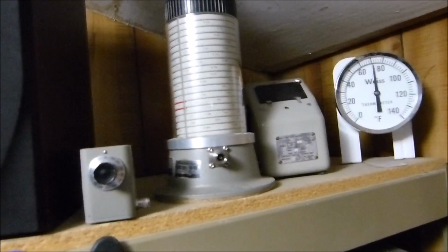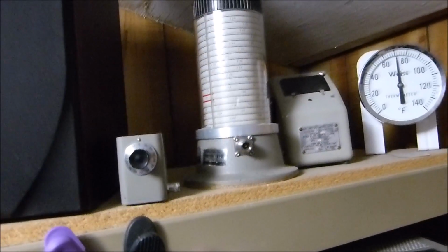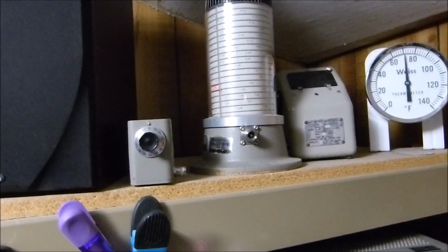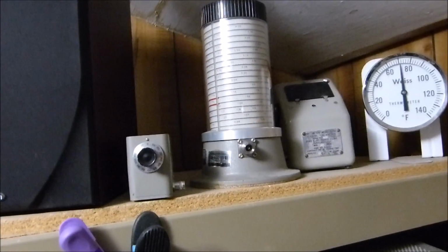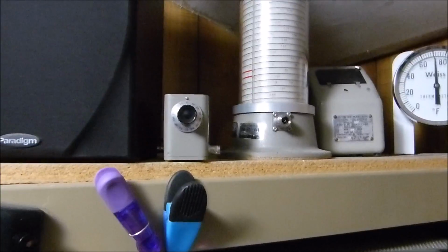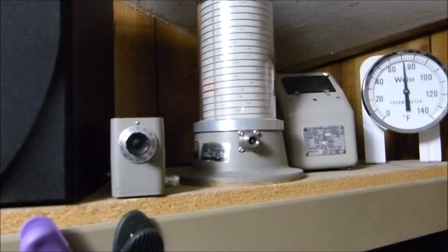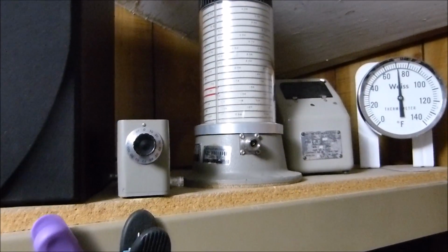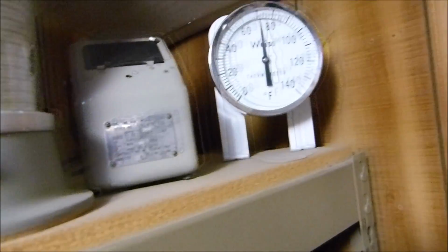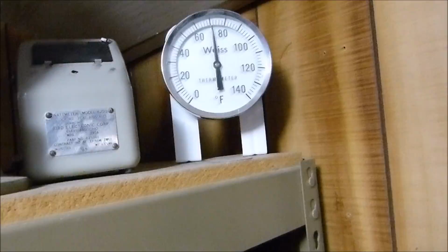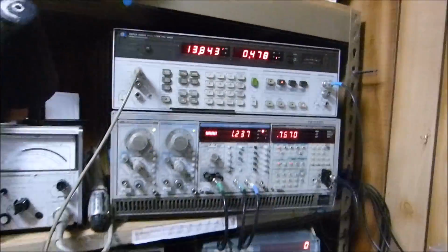There's an old frequency meter right there that you've got to use a detector with. You put RF into it and you use the detector, and at resonance the detector dips. And it's not much of a dip. It's a beautiful, fantastic device, but it's a pain to use. And just some attenuators and another little RF meter. And I trust this guy right here. I'll watch this because this is a temperature gauge above all of this equipment.